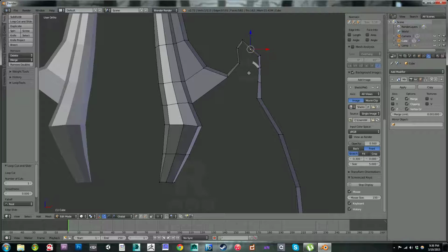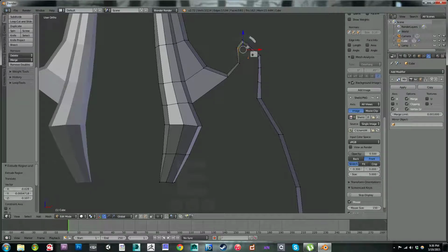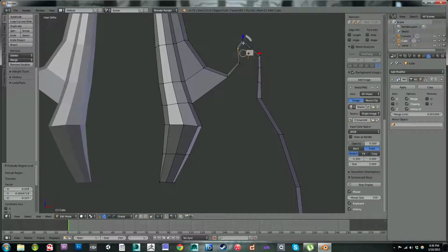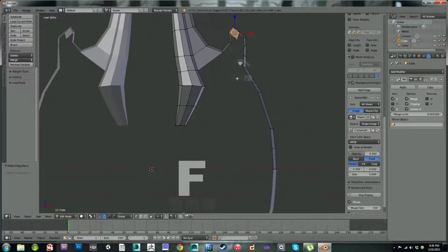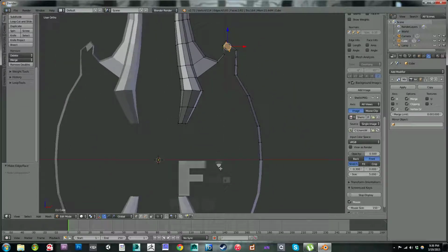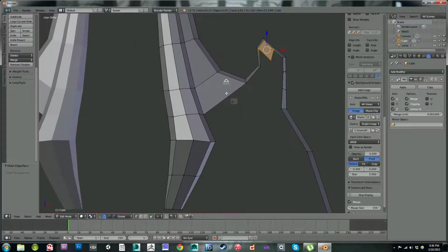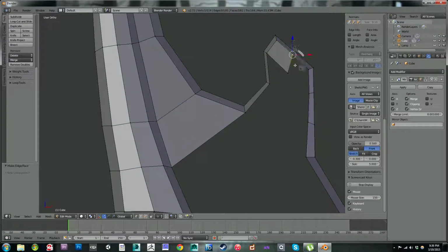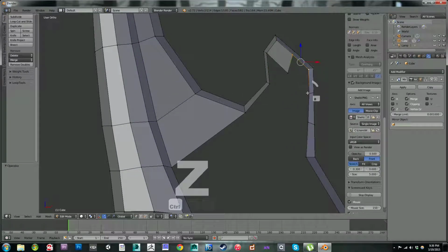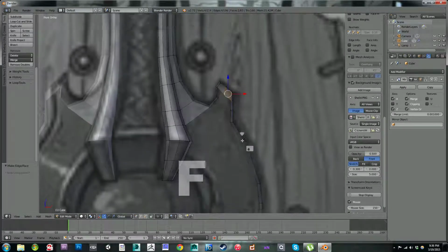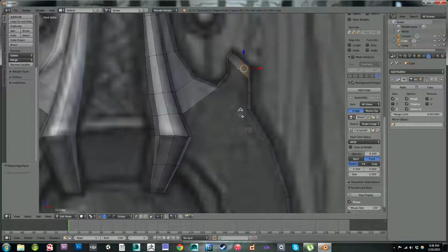And then now we've got another edge loop coming in, and that can handle some of the polys that we'll need to fill in these side faces, because we're introducing another edge loop, so we'll have enough verts to have appropriate detail. Okay, good.